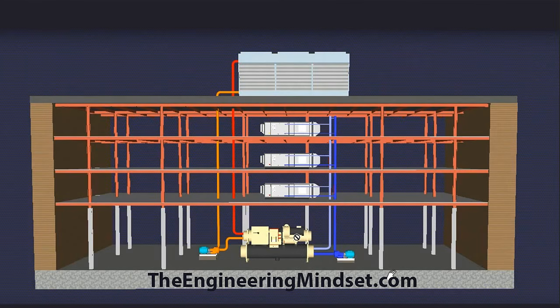Just to run you through this again. Here we've got the evaporator on the bottom of the chiller, and that's where the chilled or the cold water is produced. So that chilled water is then pumped up through the riser and then taps off of there, enters the floor, and then enters into the AHU, and we're going to be looking at how that gives off its cool. So that cold water, chilled water will be entering into a coil inside there, and the water then returns through that into the riser.